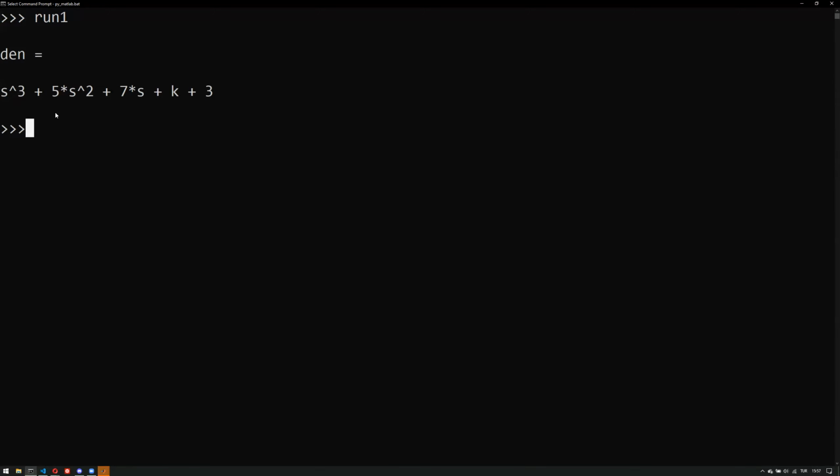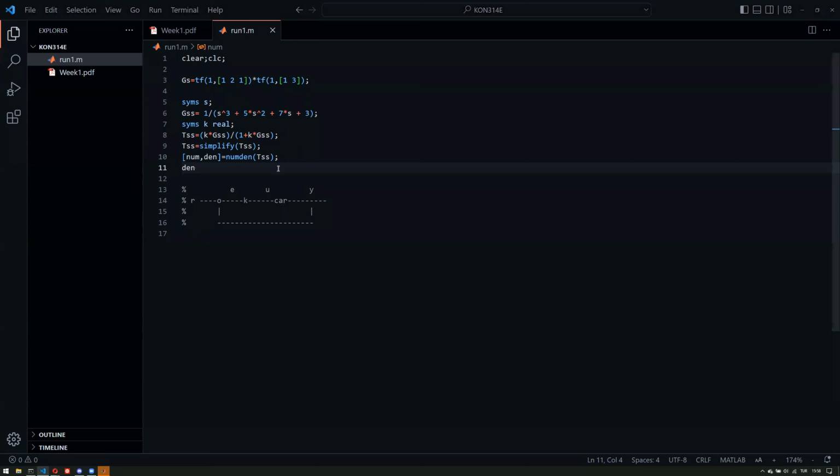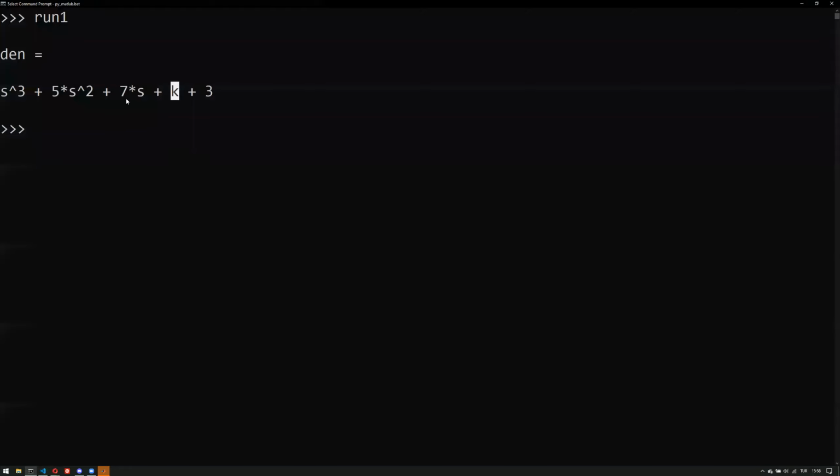Still, we have some powerful tools. One of them is root locus. Now, what we might want to do here is plug in some values for k and then look for the roots of this polynomial. And once we've done that, and if we combine all the roots and k values on a single plot, that would be the root locus itself. So we can do that by, first of all, taking the coefficients here. So if you remember from last week, we use the symbolic variable that is s in this case. We want to look at polynomials in terms of s.